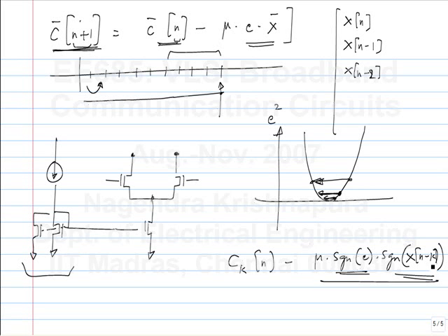Let's say the coefficients are near the optimum. In one time interval, it will increase by mu. In the next one, it will decrease by mu, and so on. That's what will happen, right? Because the sign of the error is opposite in each interval. But you don't want that kind of coefficient bounce. How can you reduce this? Take the average. Yeah, that is what you have to do.